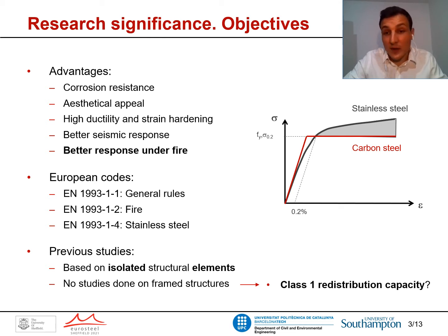Therefore, if we want to assess the real response of a stainless steel structure under fire situation, we need to use an advanced numerical model based on the mechanical and thermal properties of stainless steel. It is true that in the last years the response of stainless steel structures under fire has been studied, and therefore the upcoming version of the Eurocode 3, the Part 1.4, will include a specific formulation for stainless steel structures under fire. However, this formulation is mostly based on experimental and numerical tests of isolated elements. Therefore, the global response of the structure is not considered, and the possible redistribution capacity of internal forces is dismissed.